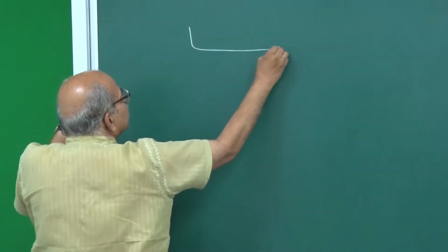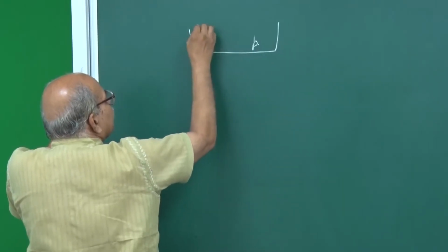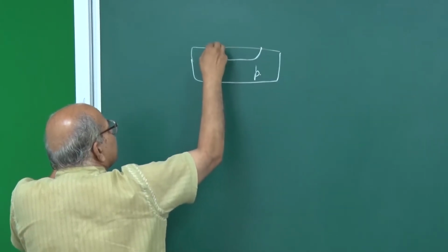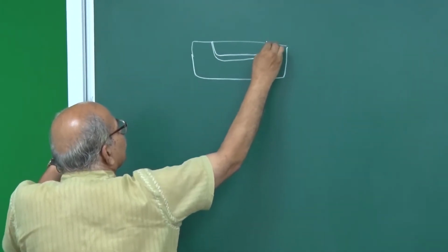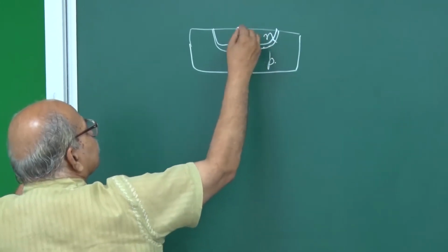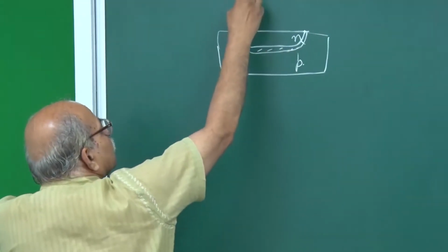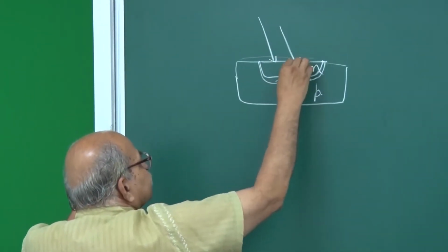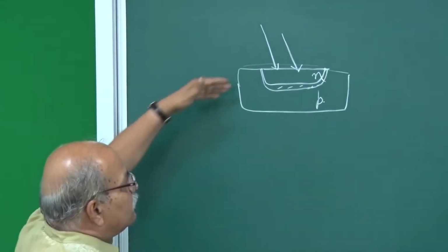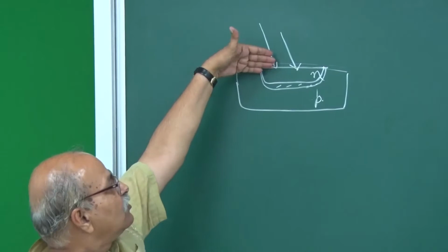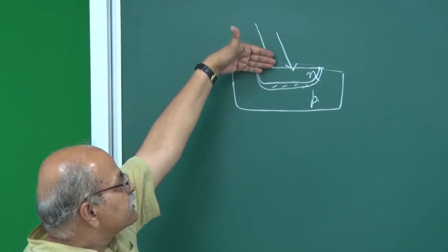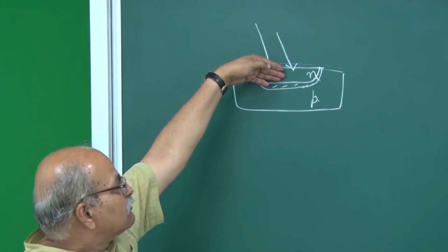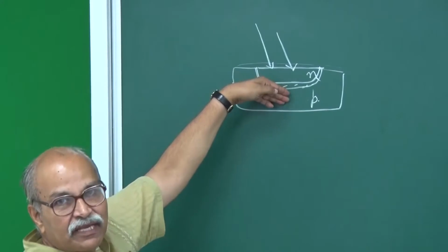You take some P type first, and then you diffuse N type on that and make a depletion layer, so that you have this PN junction, and this is transparent. So, you put some transparent layer, so light falls on this, and depending on the wavelength, depending on the absorption properties, these photons may get absorbed here, may come to the depletion layer, or may come here.